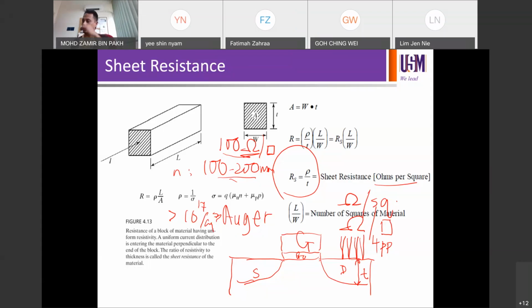Remember that when you incorporate impurities into the silicon lattice, in some cases you may also induce formation of defects. Defects are SRH recombination centers. So you will probably end up with more SRH recombination as well, which will affect the ideality factor of your PN junction, right? We will discuss that later in solar cell.